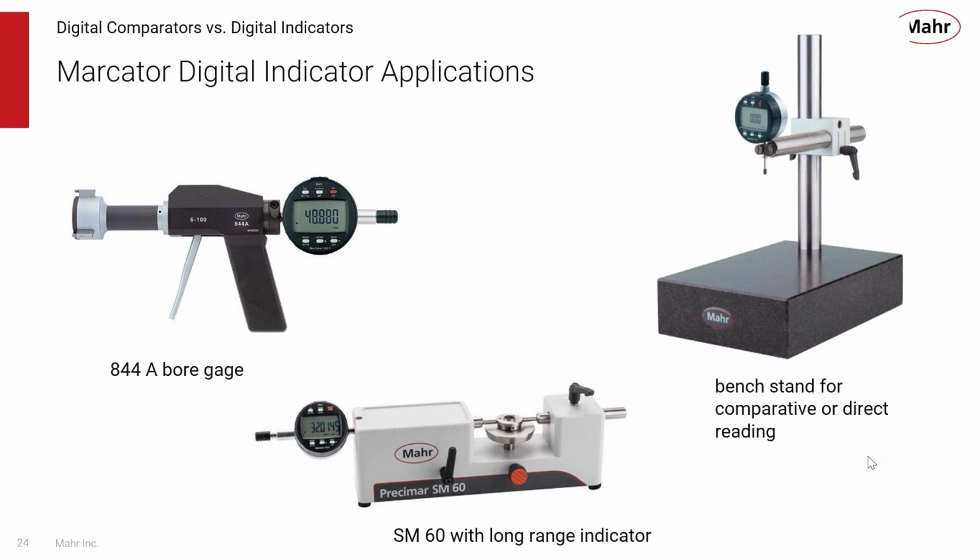Some examples of applications for digital indicators: we see them often used in bore gauges, bench style ID/OD gauges, or in stands for absolute style measurements. These are typical examples of where you see these types of indicators being used. In all these applications, you can also use a digital comparator to get higher accuracy at the expense of range.